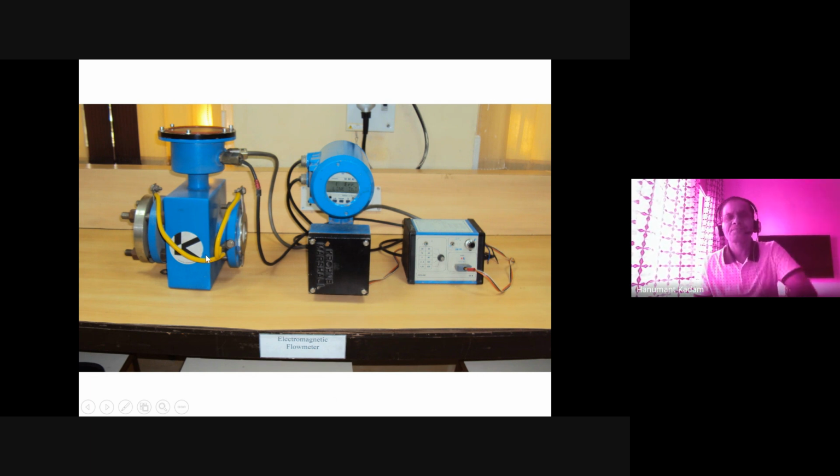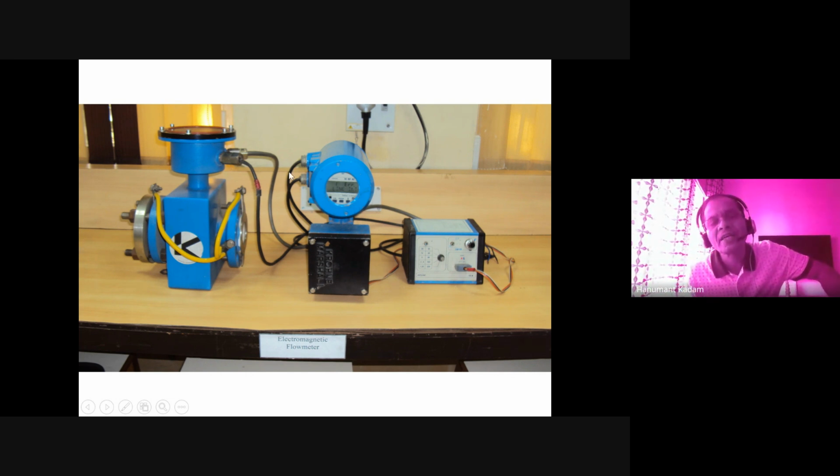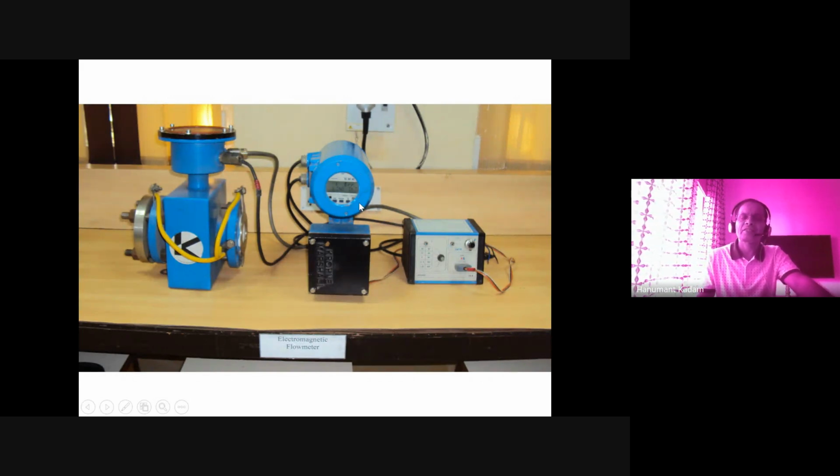And this is the earthing connection. And coil connections are coming like this. You see here, the coil connections inside go to the coils. And normally, even though we say bidirectional, you see the arrow is showing a directional flow. The flow should be in this direction. Then this is the transmitter portion, right? Whatever the transmitter means, you can see here the electrode wires are coming and connected inside the transmitter, and 110 volt supply goes to it, or 230 volt based on the coil you are providing here.